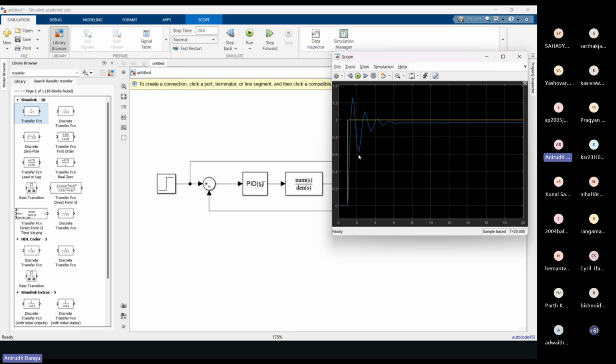So as Kunal mentioned earlier, you have these criteria like rise time and percent overshoot, and you basically try to find the optimal values for what you want to achieve. Let's say you want to achieve the minimum rise time, and you don't really care about the steady state error. It has to be within some value, but you are more focused on rise time. You put the values according to what you want and check the performance of the controller.